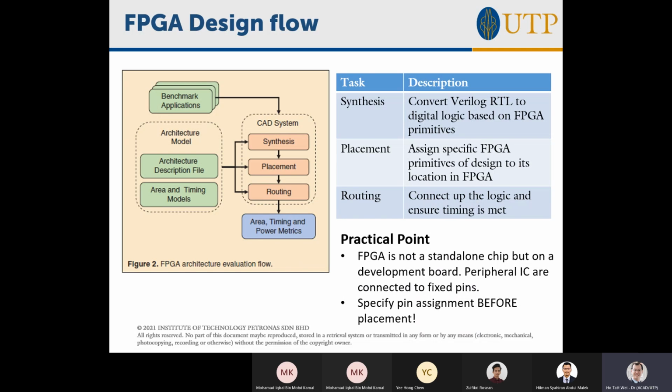And in terms of FPGA design, when you're designing to implement on an FPGA, you just need to write the Verilog in such a way that it will be able to synthesize, and then you can place and route it. Okay, so once you can write your Verilog RTL, you just click a button, and it will do the synthesis, placement, and routing for you.